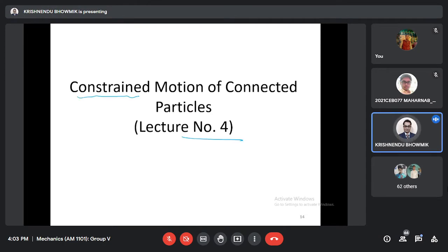That is constrained motion. So motion has been restricted using some constraint or some other means, such that movement will be regulated. Say you have one shaft and another shaft, and there is a belt; using the belt, you transfer motion from one shaft to the other. That is also constrained motion. When you have your watch, it has hands for seconds, minutes, and hours, restricted by a gear ratio of 1/60, so that you get 1 hour as 3600 seconds. Those are also some sort of constrained motions, restricted by other means.